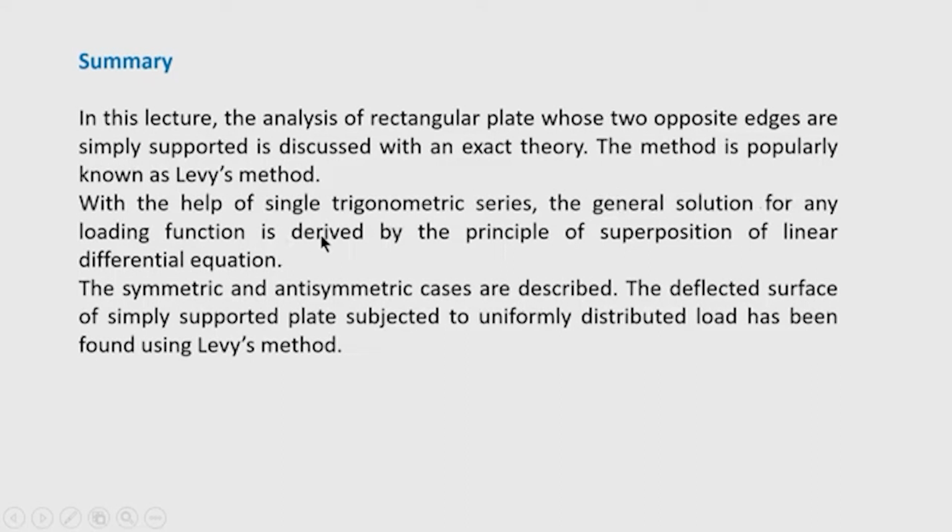We have derived this general solution for the function y, for any loading condition. Particular integral of course has to be found out depending on the nature of the load. I have told you that the best method to apply in the plate problem is the method of undetermined coefficients in the theory of non-homogeneous linear differential equation.